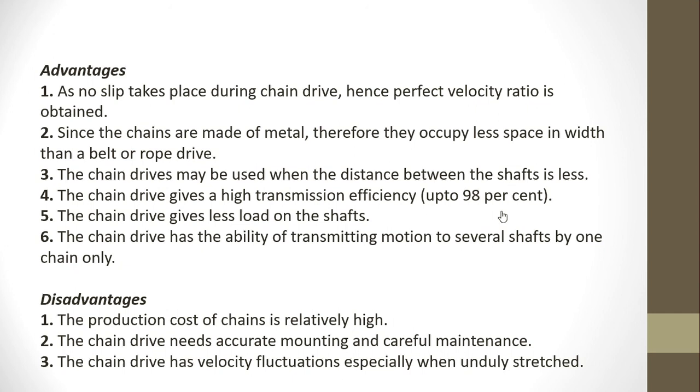They are very good even when the shafts are very near to one another, and they have very good transmission efficiency, that is 98%. It's very good. And the chain gives less force on the shafts when they run, and they have the capability to transfer the motion to several shafts. So what are the disadvantages over here?